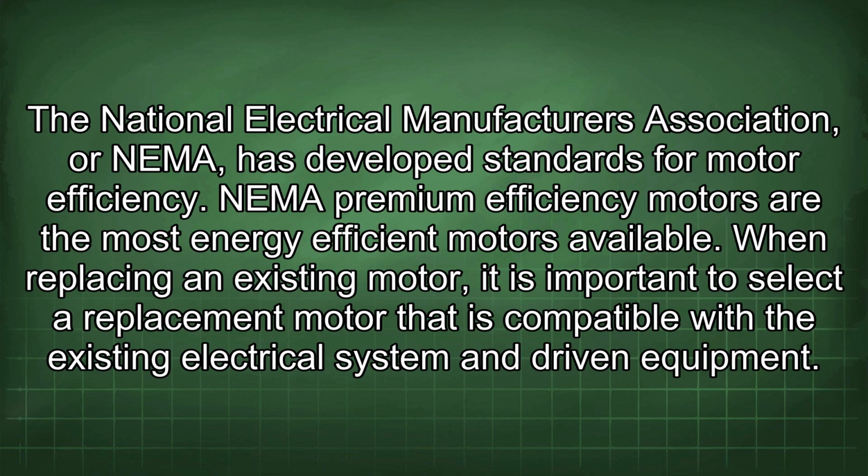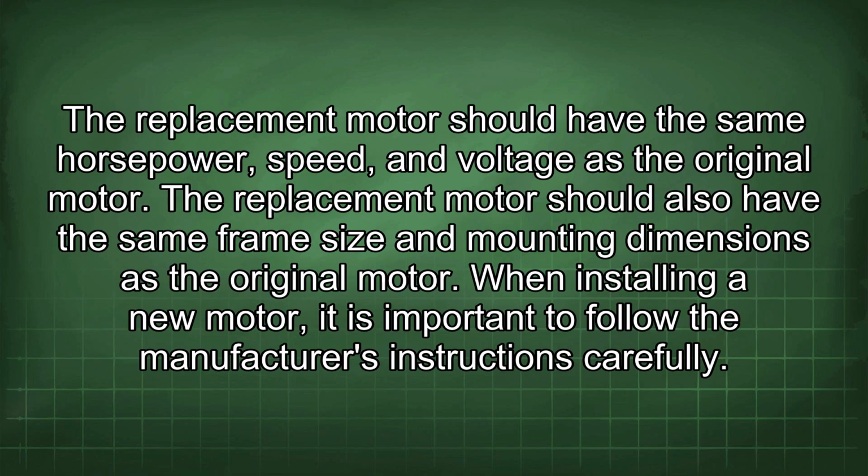When replacing an existing motor, it is important to select a replacement motor that is compatible with the existing electrical system and driven equipment. The replacement motor should have the same horsepower, speed, and voltage as the original motor. The replacement motor should also have the same frame size and mounting dimensions as the original motor.